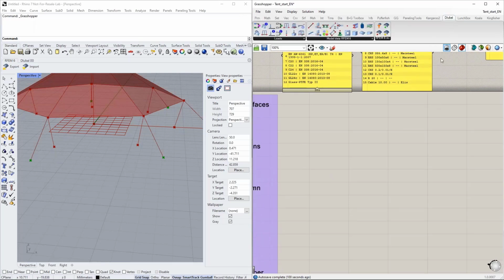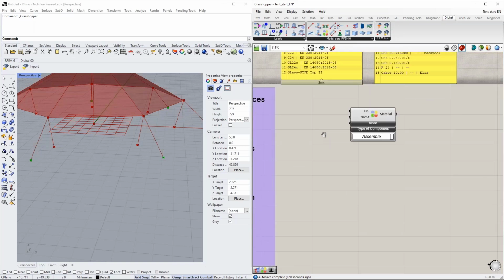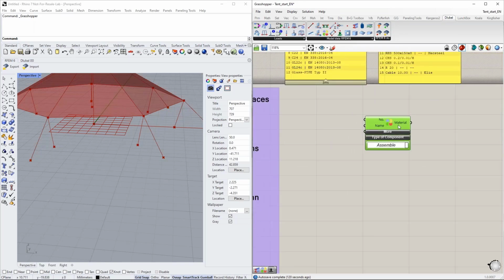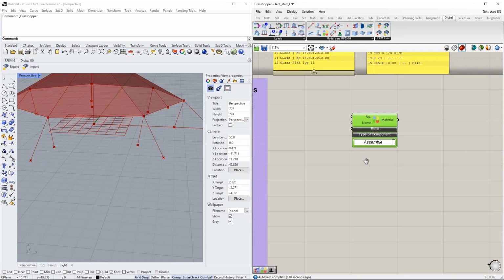And to do so, I can call up the Dlubal menu in Grasshopper. This will show up when you install the plugin. And then you have these 3 categories: the model data category, the load category, and let's say the export import category, or category with the functions. In the model data chapter, you have here a component for the materials, and you simply define the inputs and you get the material as an output.